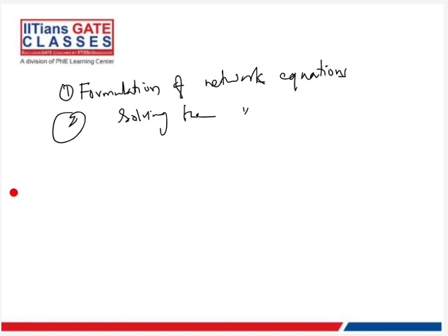So when we are looking at load flow, I said bus, right? So we have four quantities, I told you: P, Q, V, and delta. So at any given node, we tend to know at most two variables. So we know two values, and don't know two values. So based on this combination, we have three types of buses, right?